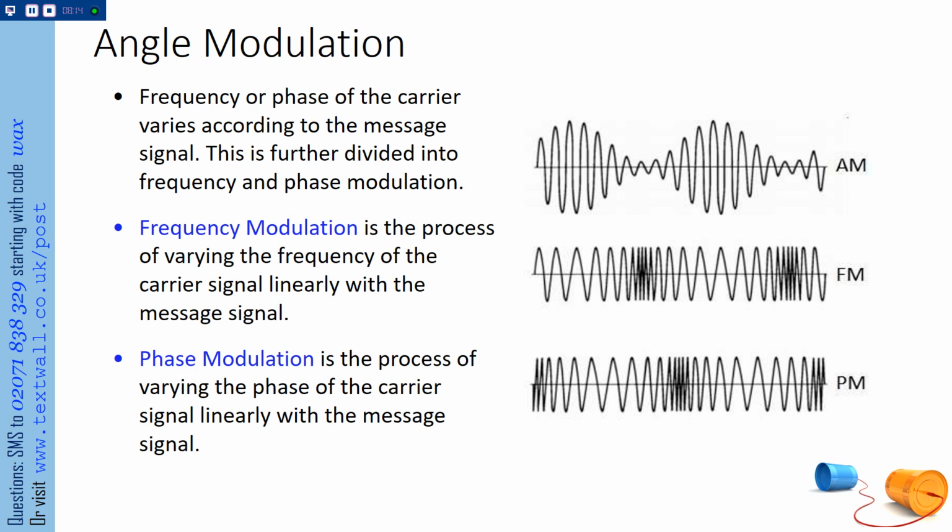So look at the FM signal, look at the PM signal. They're almost exactly the same, aren't they? So here, when the amplitude of the original message, or the envelope here, is maximum at the top, the frequency looks like it's a minimum. So the frequency and phase appear to be out of phase. So what's changing in the frequency is the instantaneous frequency is changing. What's happening in the phase is the instantaneous phase is changing. We'll talk about the relationship between phase and frequency in a minute.